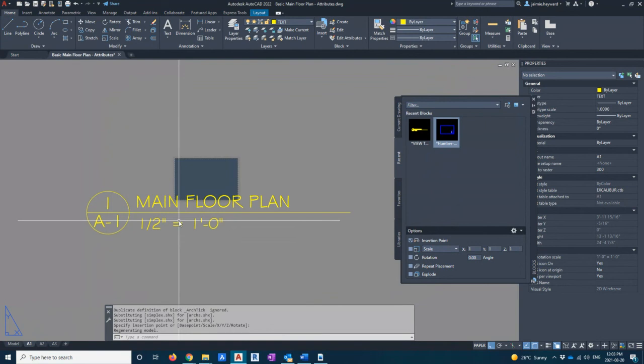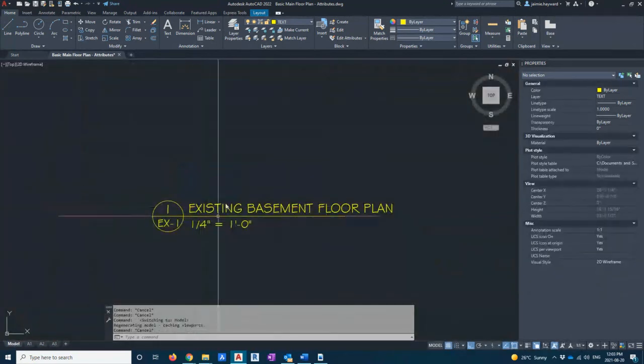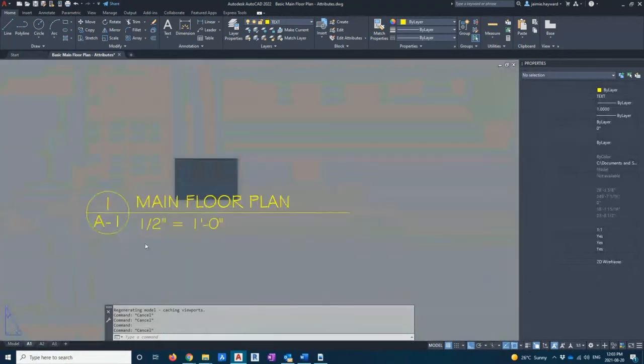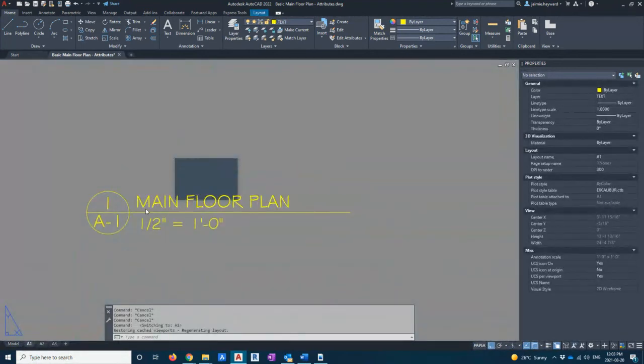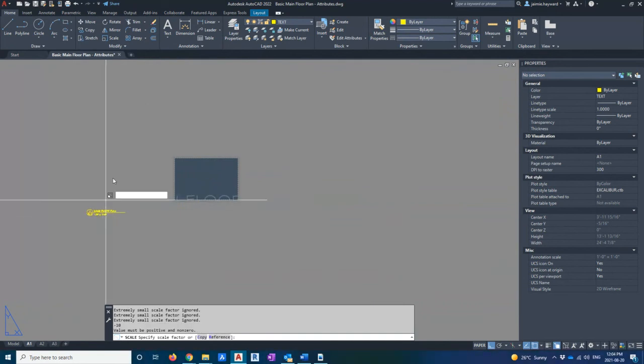Okay. Now, let's say, for example, this has happened, and the scale of your objects are completely massive. They're way too large. Let's go back and edit that. I'm going to close my insert box, and I'm going to go back to model space. We need to scale this down. But I can't just scale it the way it is now. I mean, yeah, you can. So option one, I'll give you options. Option one is we just use a scale command on this. SC enter. I click my scale, my object, sorry, base point. And let's say I want to scale this down 10 times. Oh, not up, -10. There we go.